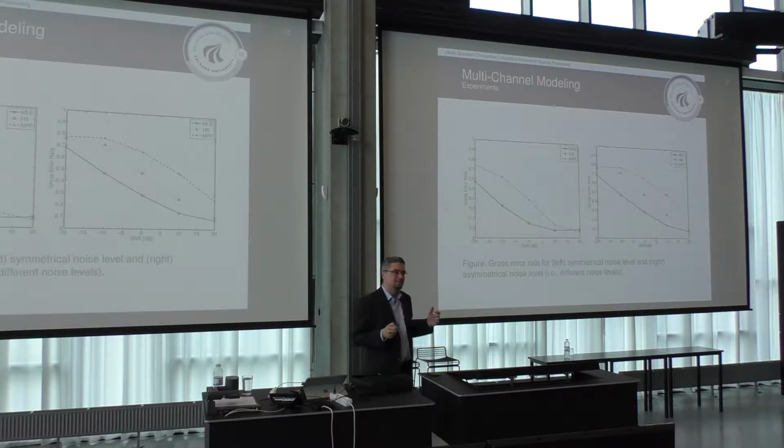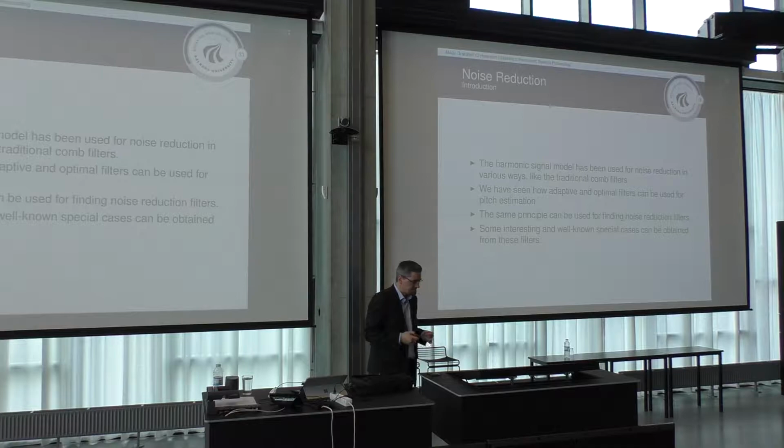That's not surprising, because when the noise level is the same, then the harmonic summation is the same as that method. But when you change the noise level in the different channels, you see the picture change here. The harmonic summation method starts doing way worse, but the one based on the principles here still performs quite nicely. So you see, in a really simple way here, you could actually gain an estimator that's more robust to noise. Okay.